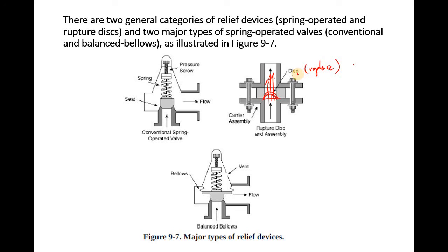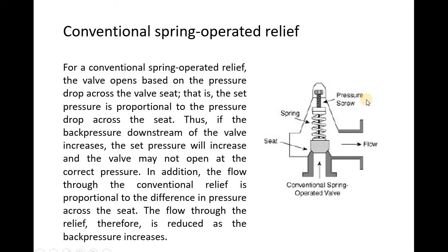Replace the disc, and usually replacing the disc is not expensive. We use cheaper discs that you can use. So you just put a disc here, it's broken, put another one, it's broken, put another one, and so on. But I cannot say it is preferable here, because it depends on what explosive material or what kind of gas you're exposing here, and whether you will allow for maintenance here or not. So all that has a meaning as well. And here, will you allow for materials that have a lot of contaminants or not? We're going to see that.